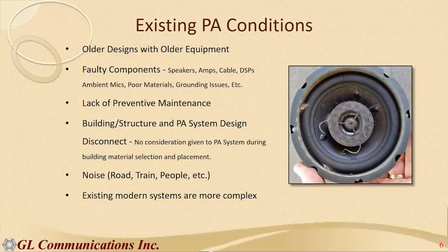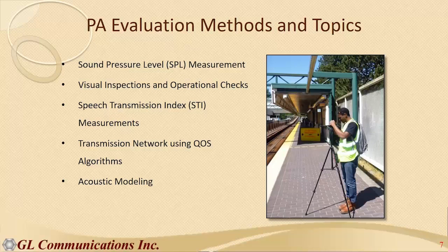Okay, so we'll talk a little bit about some of these things. Even with existing modern complex systems, there's a lot of cutting edge PA systems that have just been installed in the last few years. Where we found that problems may happen there is not necessarily in the design or the materials or the components. They're fairly new. It's typically with the configuration of the system. Maybe the installer did it and they say they've done it right, but it always is a good idea to have a second set of eyes look at it if you're having problems at a location. DSPs can be configured wrong, ambient mic levels can be configured wrong, things of that nature. So even complex new systems have issues, and they're typically due to configuration.